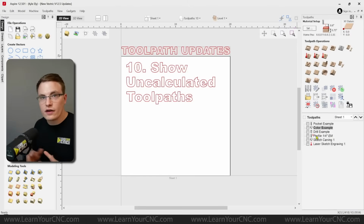This will save you a lot of mistakes because sometimes you may save your G code without calculating a toolpath, and when you go to cut it on your machine, it's not doing what you want it to do, and that may have been the reason. In older versions, you didn't know that. They all look the same. Now in version 12.5, we have that ability to quickly see that toolpath is uncalculated. So another one of those minor little things that makes a big difference.